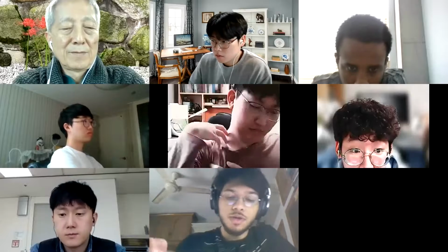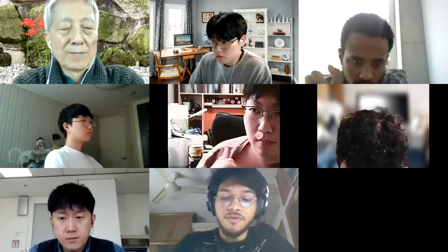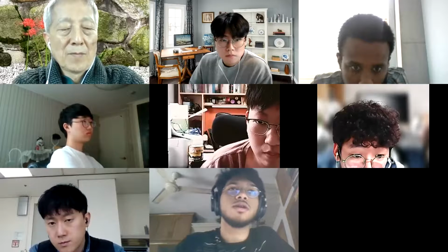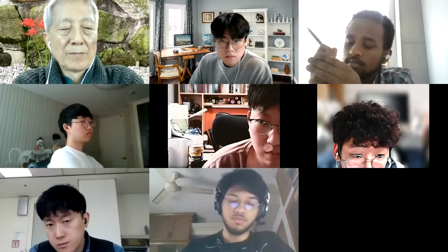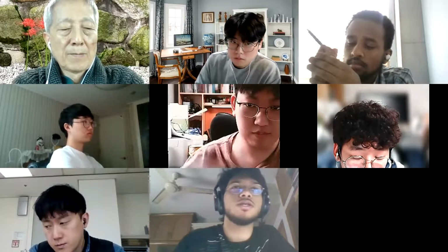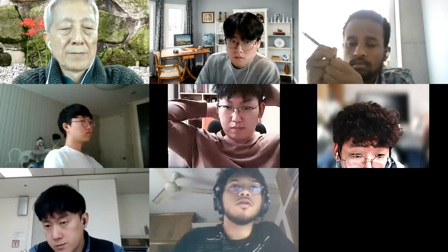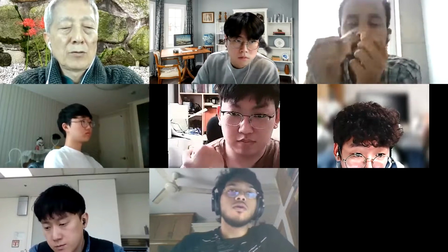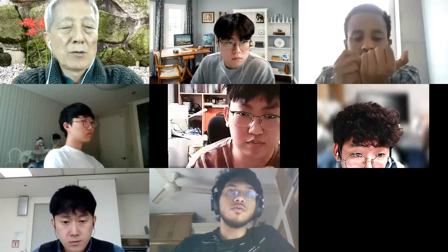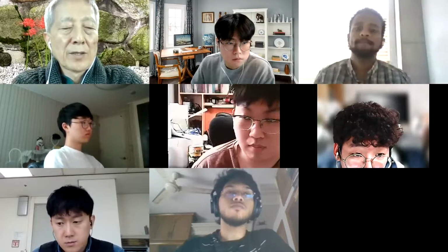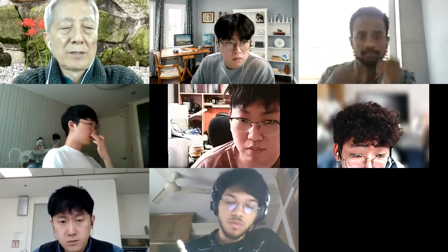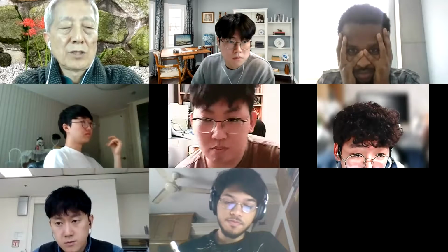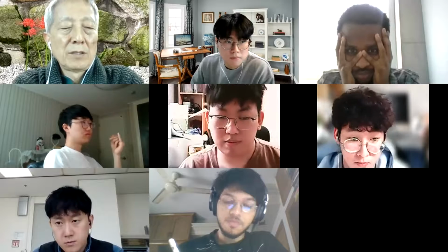I had two questions actually. Good. For the waterline, are the units in meters, like 2 meters from? So, for example, waterline 2, what does that actually mean? Oh, usually they do not correspond to an absolute unit of measure. These are just numbers. Okay, as a measure, you need to start from the draft length.